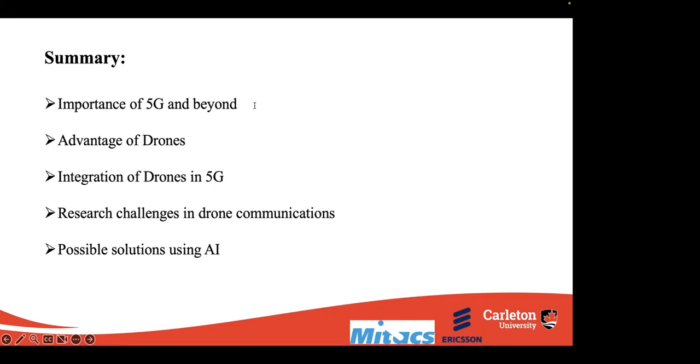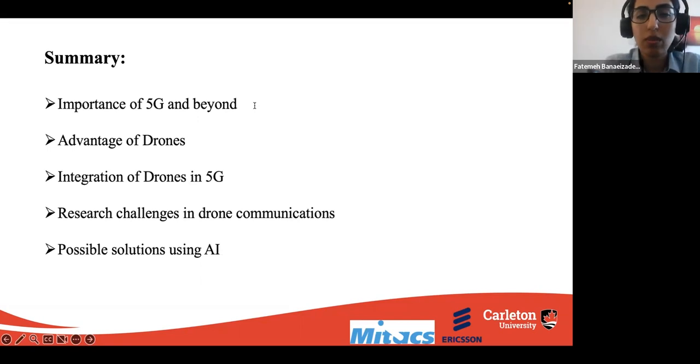Okay. And another technical question, do you see NOMA to be a more useful technology compared to OFDM technology for 5G? I think, yes, NOMA is more useful than OFDM. NOMA is going to allocate one resource block to several users. But OFDM allocates an orthogonal resource block to each user separately. In NOMA, it will allocate 2 or 3 users, depending on how many users we have in our network in one resource block. Then here we have mutual interference between users, and we have to optimize the power for users which are using the same resource block. Okay.